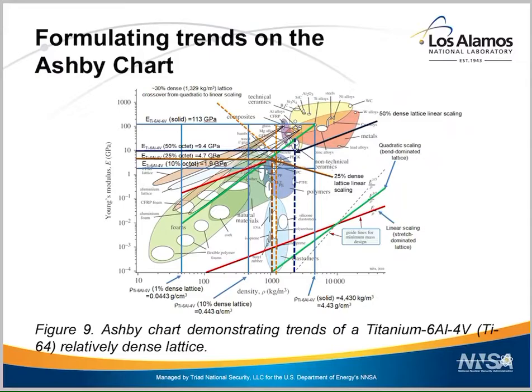Once the lattice unit cell models are updated with an appropriate and agreeable Young's modulus to the calculated effective modulus, these data points will be plotted on the Ashby chart to approve or disprove a uniform quadratic scaling agreement between stretch-dominated lattices, that is, the octet, and bend-dominated lattices, i.e., a rhombic dodecahedron, after a certain relative density range that is presumed to occur at 30% to 40%.